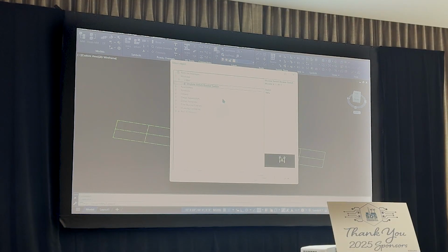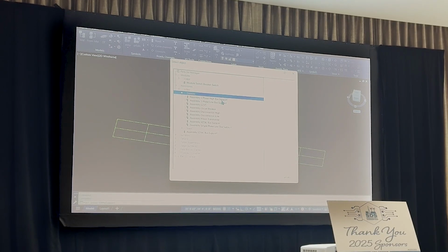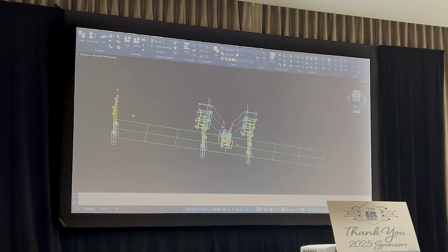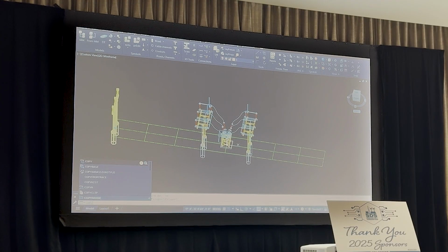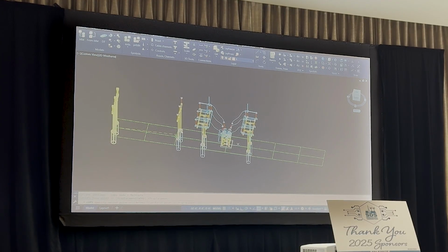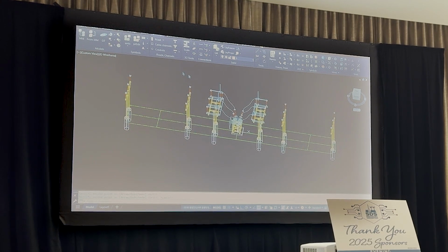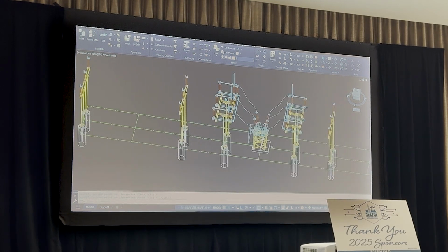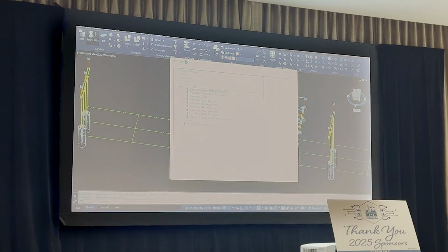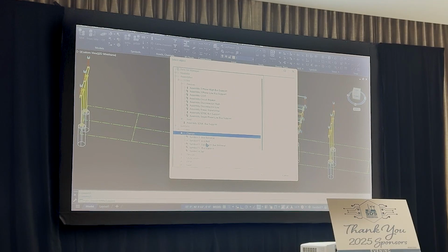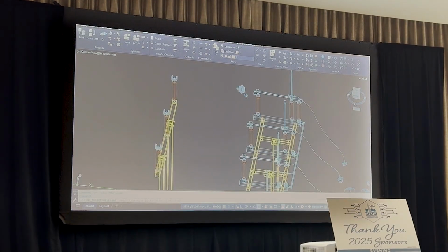And then from here, I could place a few more assemblies. So here I'm going to go high bus supports now. So I have one that goes here, rotate, 90, copy. And I could place that in all 4 of these. And then the only thing left here is to place these fittings and run bus. So I'll go ahead and place a few of these fittings again. We'll use these expansion fittings.